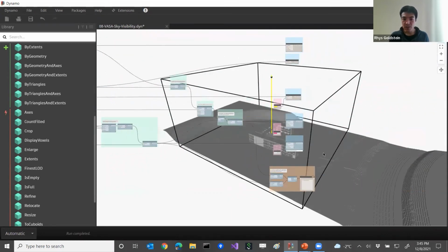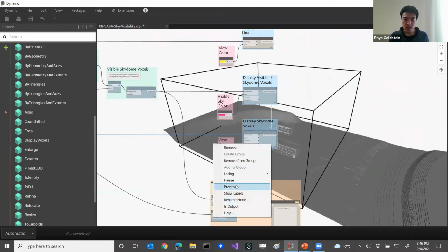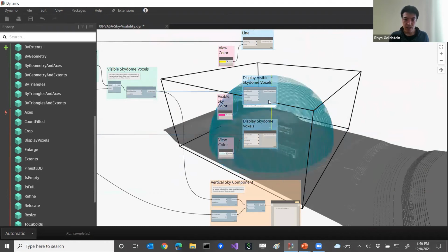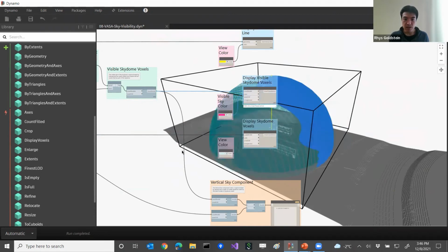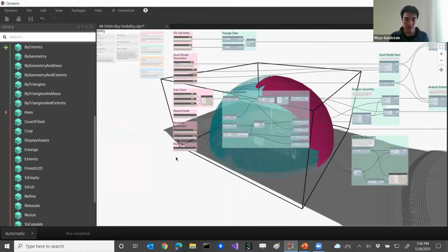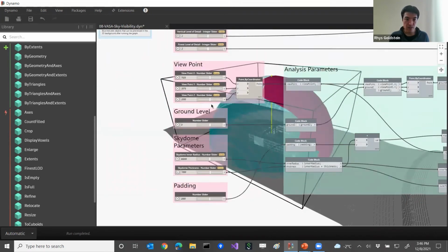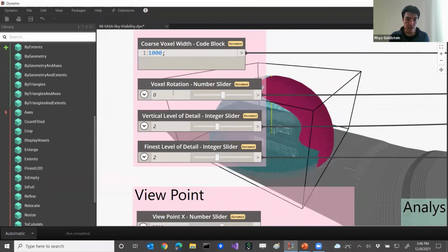One thing that's nice about this trick is it lets us rotate the model, because if we get our extents from a cylinder, it means that our extents will remain large enough even if we do a rotation. So if I find the rotation angle over here, box rotation, let's set that to 45 degrees.